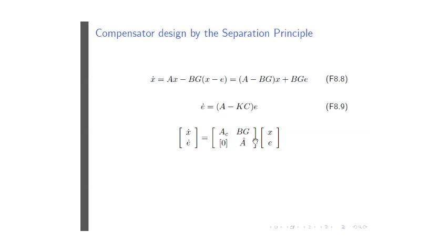Now, of course, if I've opted to use a reduced order observer because some of the states are available directly, let's say once again I had a 4th order plant, but two of the outputs made it possible to actually know what two of the states are, and because of that I opted to design a 2nd order reduced order observer, but that is 2nd order. In that case, my new A matrix will be 6 by 6 and not 8 by 8. But let's for now stick to the full observer case. So I've got this 8 by 8 matrix.